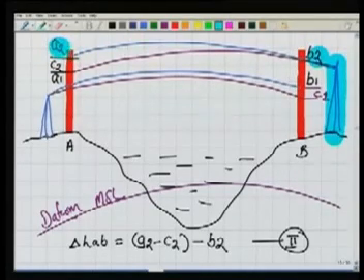Again in A2, the bisection should have been at the point here. I should have seen this, I should have read it. But because of the error, I am not reading this, rather I am reading somewhere here at A2. So I should apply in A2 the correction which is equal to C2.